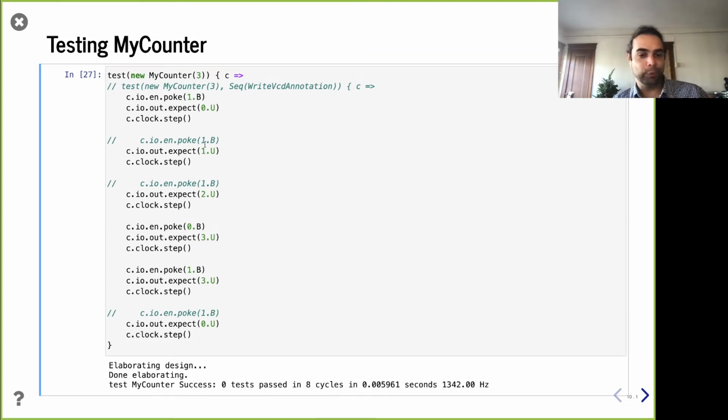Sometimes, when we're running a test bench, it's a little bit easier to just have all the signals there. It depends on the test bench, right? If you have all the signals every cycle, it can be very verbose, very long, a little tedious to read and write. However, sometimes it makes it really easy to quickly change things, or if I want to change a value. So if you look at my own test benches, I do both styles, where some have every signal, every cycle to be very clear what I'm doing. Other times I only record them when they change.